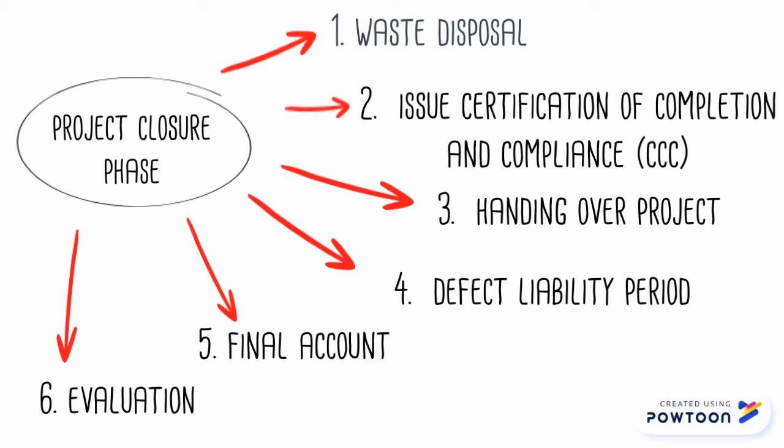The PSP, principal submitting person, which usually is an architect, has to submit the CCC to the client and a copy of the certificate to the local authority and professional boards. Two weeks before the expiry of the defects liability period, a final inspection shall be held with the SO to review the requirements of any alteration or replacement in order to gain approval for final handing over. If any portions of the work are found not acceptable under any terms, the contractor shall handle it immediately before the date of final handing over.